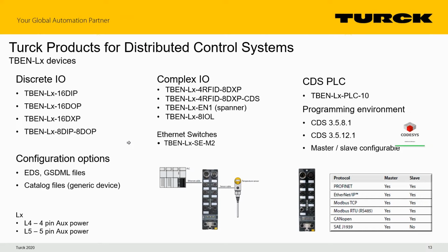Now we can put an Ethernet switch out in the field, and Ethernet is 100 meters length per run, so every time we put a switch in, we gain 100 meters. So if we have a large factory floor or spread-out process system, we can spread these switches out and make the network go everywhere it needs to go.